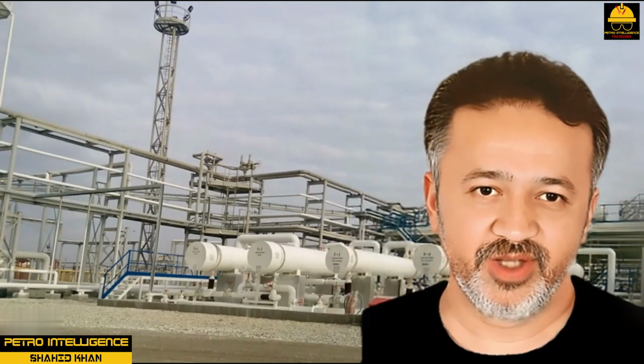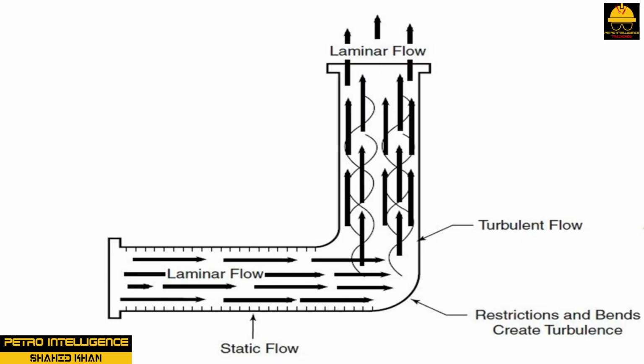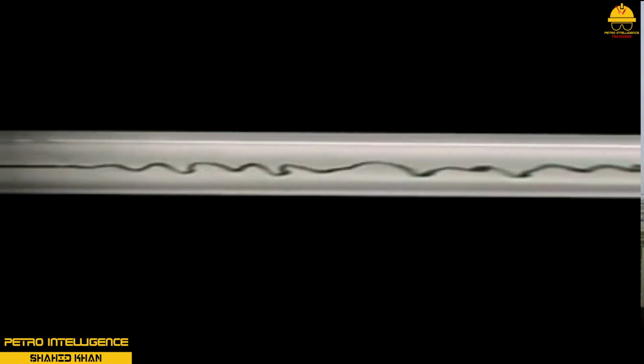Laminar and turbulent flow. Two major classifications of fluid flow are laminar and turbulent, as shown in picture. Laminar or streamlined flow moves through a system in thin cylindrical layers of liquid flowing in parallel fashion. This type of flow will have little, if any, turbulence, swirling or eddying in it. Laminar flow usually exists at low flow rates. As flow rates increase, the laminar flow pattern changes into a turbulent flow pattern.